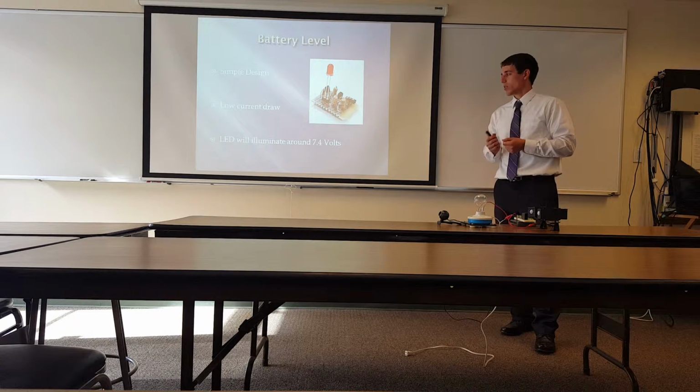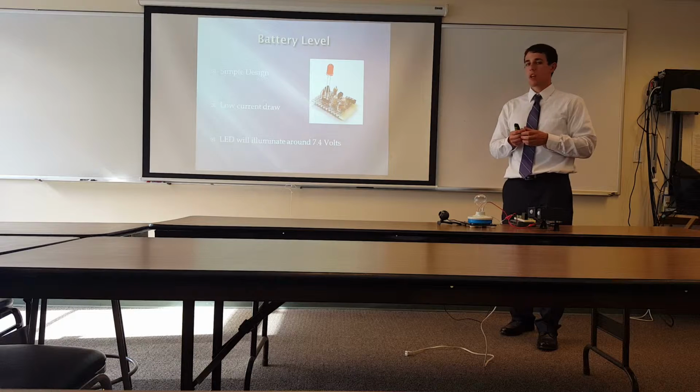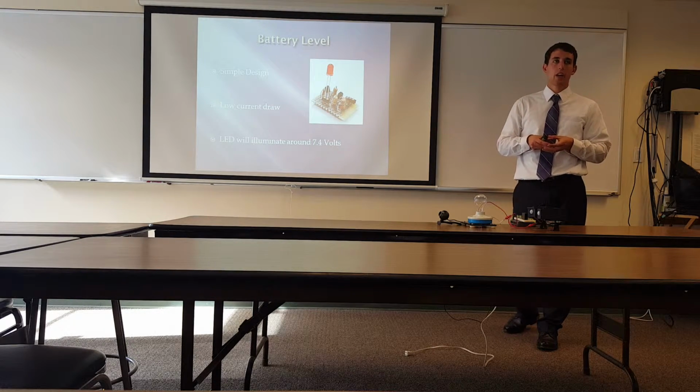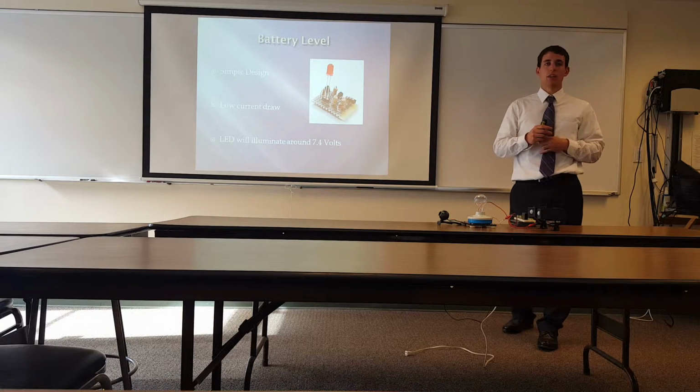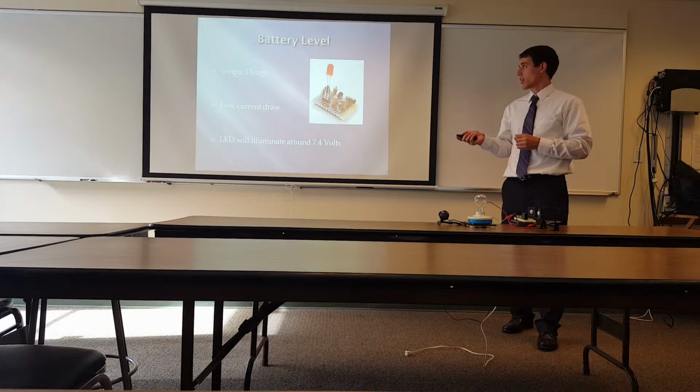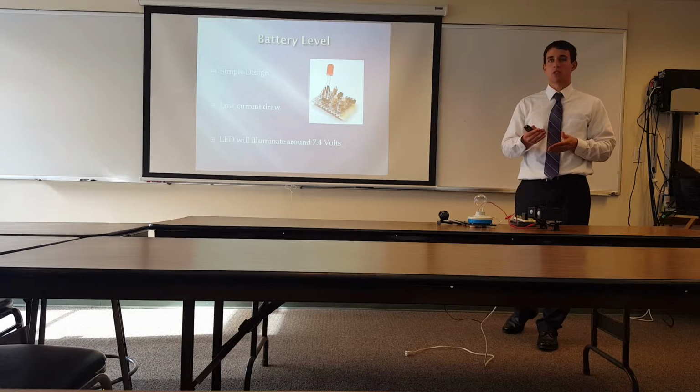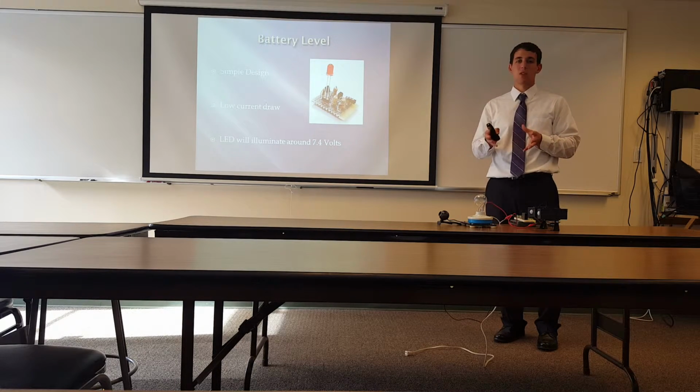So the LED will illuminate around 7.4 volts. I'm using a 9-volt battery pack. For a 9-volt battery pack to be considered dead, it has to drop down to 7 volts. So I have the LED illuminate at 7.4 to give the user a little heads up saying, hey, the battery's low, they need to be changed.